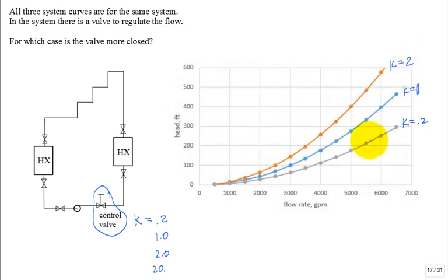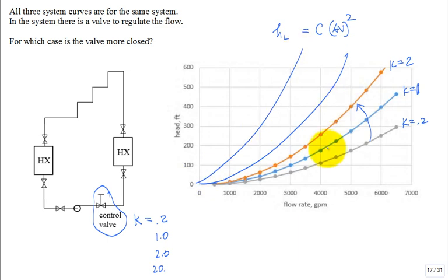So what's happening? That constant, multiplying volumetric flow rate squared, is going up. And the curves will continue to curl up as you add more and more flow resistance. It's pretty easy, isn't it? Isn't this fluid system pretty easy? So that's what would happen.